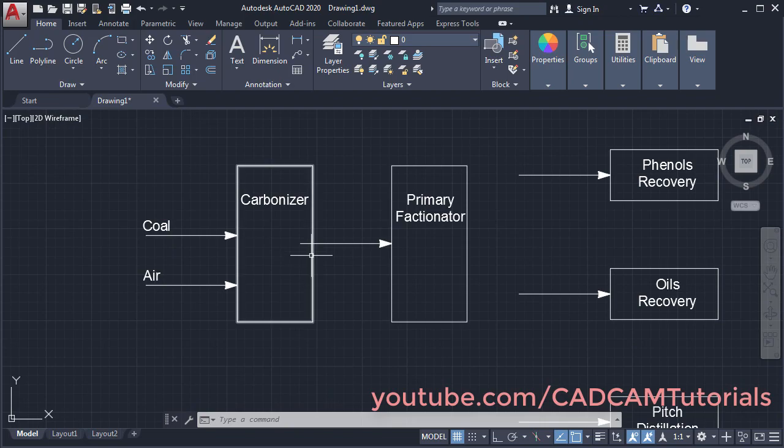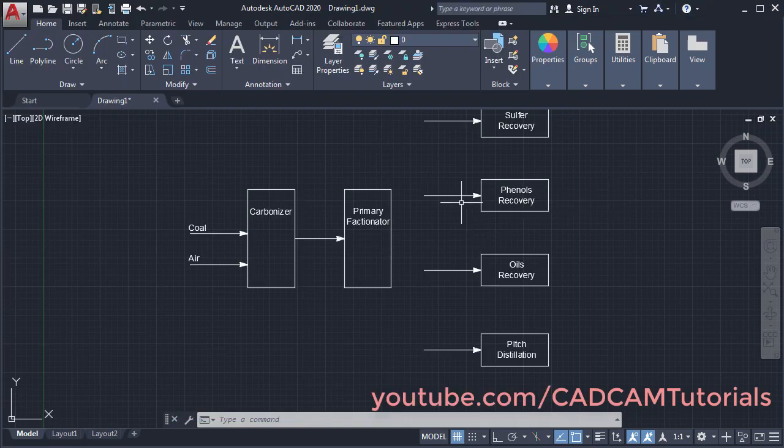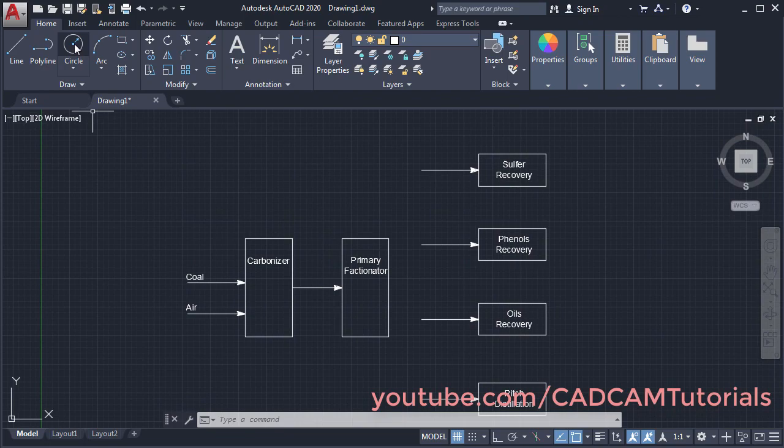Then we will trim this, for trim type tr, enter, enter and click and enter. Then next is this circle and this arrow. Click on circle, specify center point, take your cursor away and click.